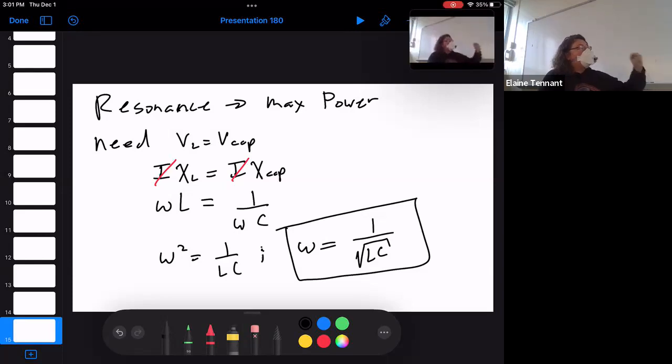Now, inductors and capacitors, they're those harmonic oscillators that have their own phase. Like capacitors will collect charge at a pace that is inherent to their capacitance. Inductors make magnetic fields at a pace that is proportional to their inductance. And so they will want to bounce their energy back and forth at a certain frequency.